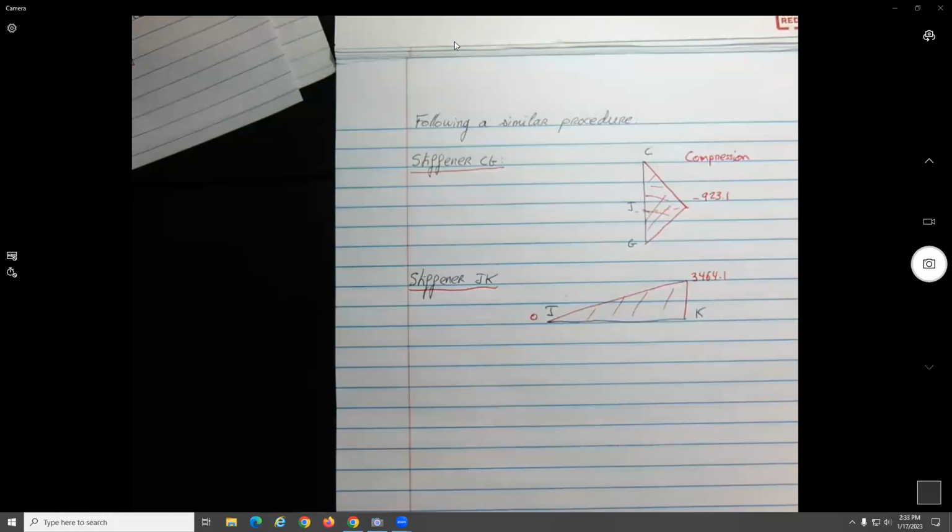Okay, so the next example is the last example we're going to do in class that is statically determinate. Actually, the problem is statically indeterminate, but we're going to solve it making the assumption to make the problem statically determinate. And we're going to see why this is a valid assumption in most cases. If you look at a truss, maybe it has a rectangle, and to be statically determinate, you can just put one bar for stability. You can solve this one as statically determinate.